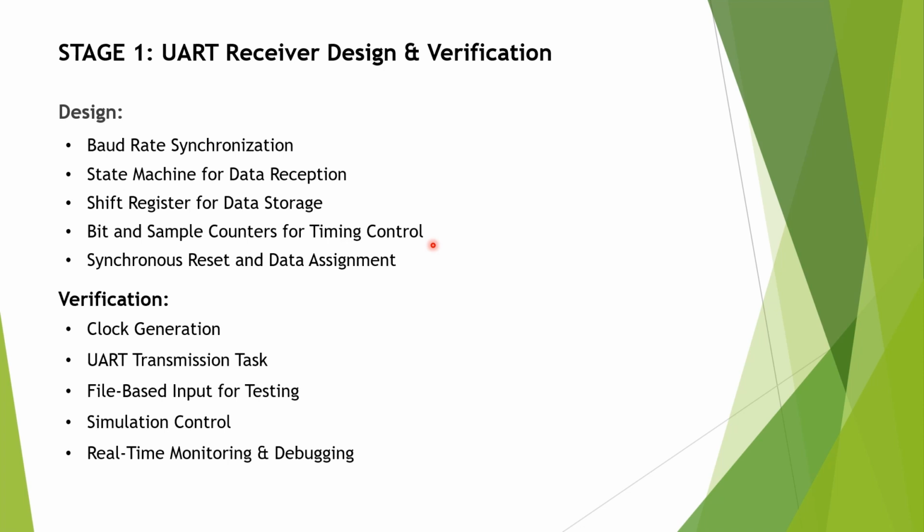Next is synchronous reset and data assign. A synchronous reset will ensure all the registers and counters initialize properly. Basically, through reset, we implement the initialization, and once a byte is received and verified, it is stored in a data register for further processing. So these are the key components that we have to implement in our design.